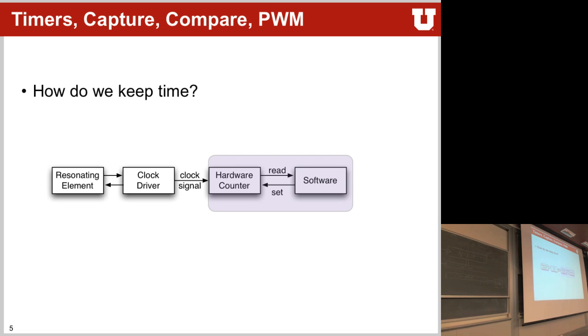So what you do is you write into your CCR0 2 to the 14 so that your counter will start at 0, count up to 2 to the 14, and then keep counting from 0 again. Right? So it will do something like this. This is time.